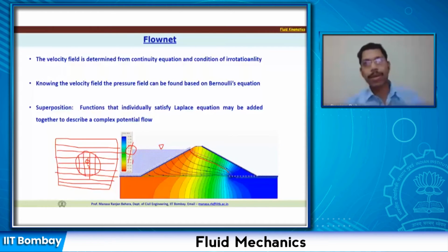These are very critical. Okay, so these are the lines that we can plot typically, which shows you the streamlines or flow lines. And you see here, these are the lines which are going perpendicular to the streamlines. This shows you the equipotential lines. Okay, so you can find out the characteristic and how the flow net looks like. And what is the advantage here? If you look at this streamline, the spacing is quite larger or spacious at this location. But as they flow and come towards this, the spacing is less. So what does it mean?